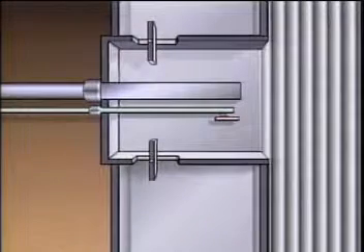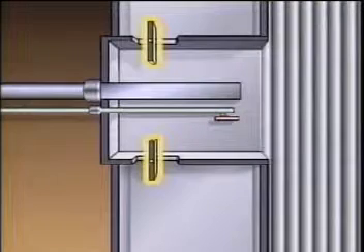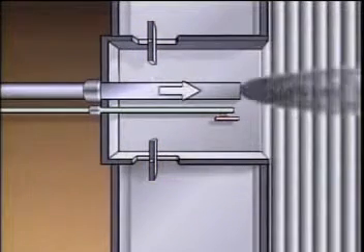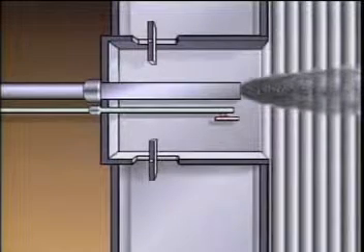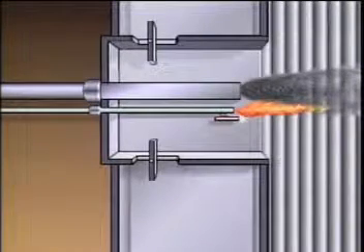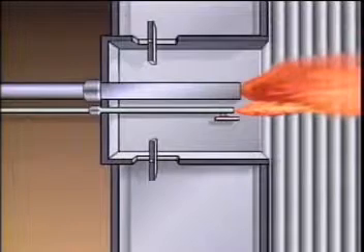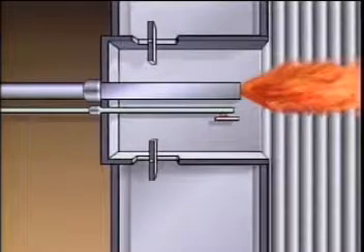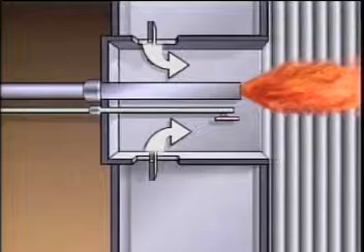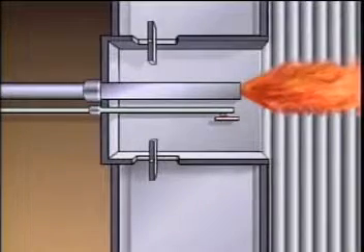A burner has 3 main parts: a fuel nozzle, an igniter, and 1 or more air registers. The fuel nozzle helps to create turbulence by spraying fuel into the boiler. The igniter provides the initial heat needed for combustion. After the fuel begins to burn, the heat needed to continue combustion is usually supplied by the flame in the boiler furnace. The heat from the igniter is no longer needed. The air registers provide a means for regulating the flow of air through the burner and help create turbulence.